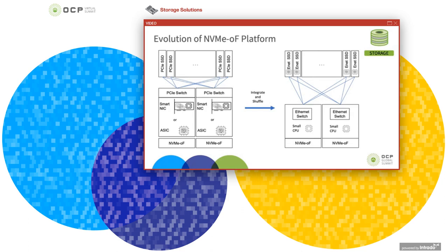And you generally have more drives in the platform than what can be addressed by a single controller. So you will see a number of these controllers being bundled together, and then you will see a PCIe switch. And the number of ASICs or SmartNICs will depend on your design goal for the bandwidth matching and oversubscription ratios between the front end and the back end.